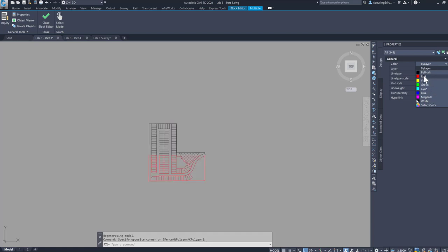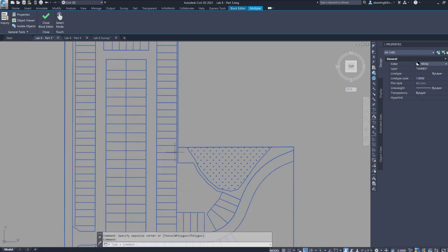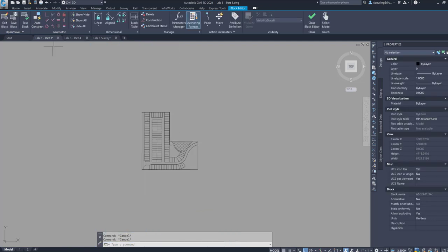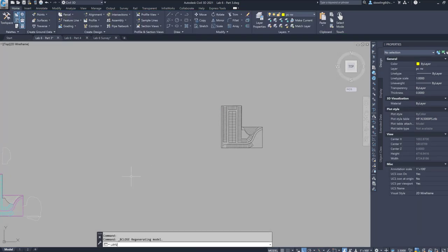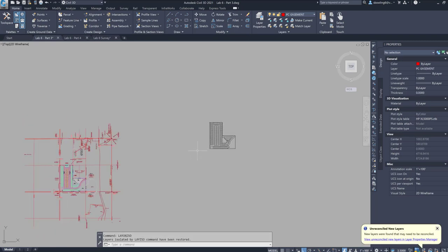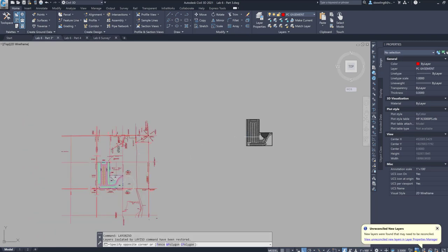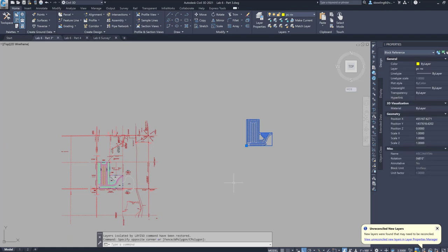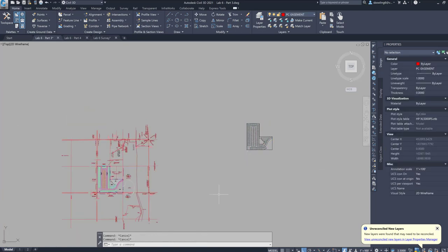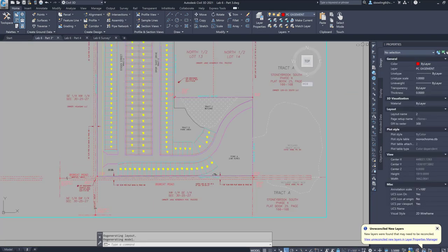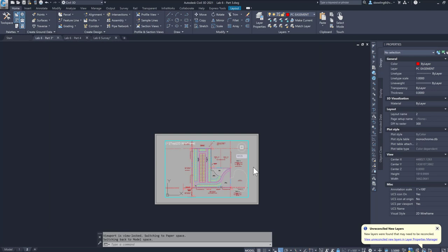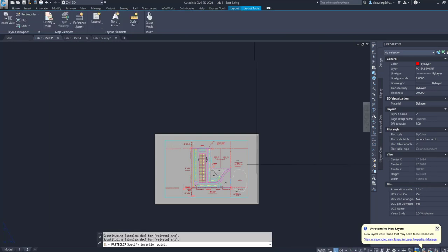I am going to turn everything white. And I am going to save the block, and close the block editor. And then I'm going to go LAYON ISO. Okay, now I have this nice block, it's one solid object, and I can do whatever I want with it. So I am actually going to go Control X, cut it from here, and paste it. Double click out here, Control paste it out here.